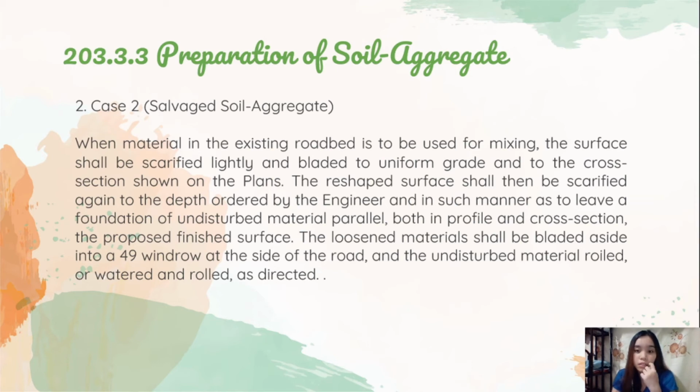Then the loosened material shall be bladed aside into a windrow at the side of the road and the undisturbed material rolled or watered and rolled as directed.